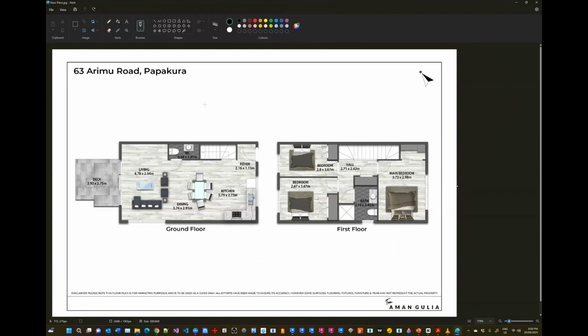So before we start modeling in Revit, let's just have a look at what we are working with here. In this area here, where my cursor is, we can see there's the ground floor, and then we've got the first floor. If we started to plan our grid layout, we would probably want to create one grid line over there. We'll have another one here, another one here, I think we'd need another one here, and I would create another grid there. So this allows us to create the deck area, which has got that width. I know that's the width because this distance here is smaller than this distance here.